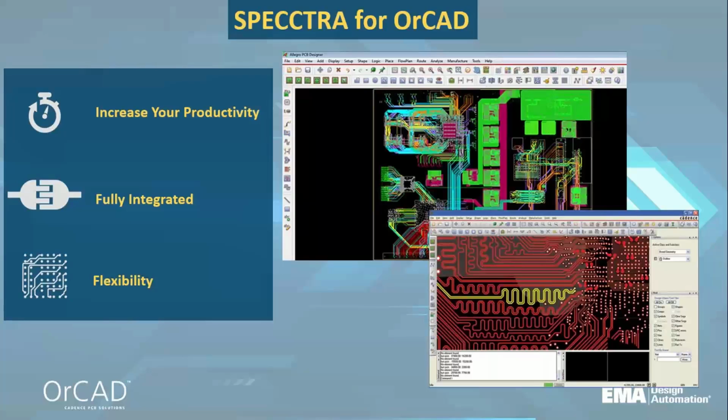It's fully integrated, so the SPECCTRA route engine is tightly coupled with the PCB tools, allowing your design data and constraint information to route and update seamlessly while you're designing. And there's flexibility also: easily choose the areas of the design you want to route and lock down, so you have full interactive routing with this tool.